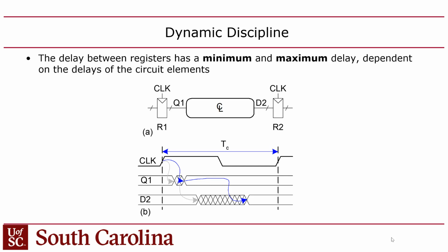On the other hand, there is the hold time. You also have to make sure that this logic isn't too fast. Because if it's too fast, this register will change on the clock edge, and then the logic will percolate through here too fast, and you'll violate the hold time of this guy, right? You have to make sure that this circuit can't be too slow, but it can't be too fast. Otherwise, this input is going to change before the hold time expires, right?